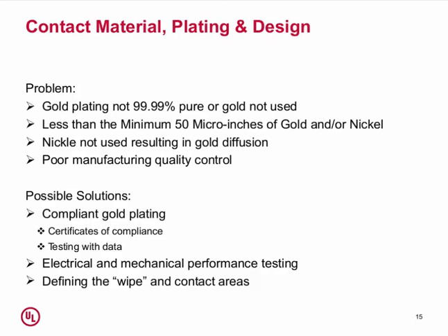And then once again, poor manufacturing quality control with respect to the plating process, or control over your vendor who's doing the plating, providing the parts, enters into it as one of the problems. Possible solutions is use compliant gold plating. Get certificates of compliance from your vendors. Do your own testing, your own checks.